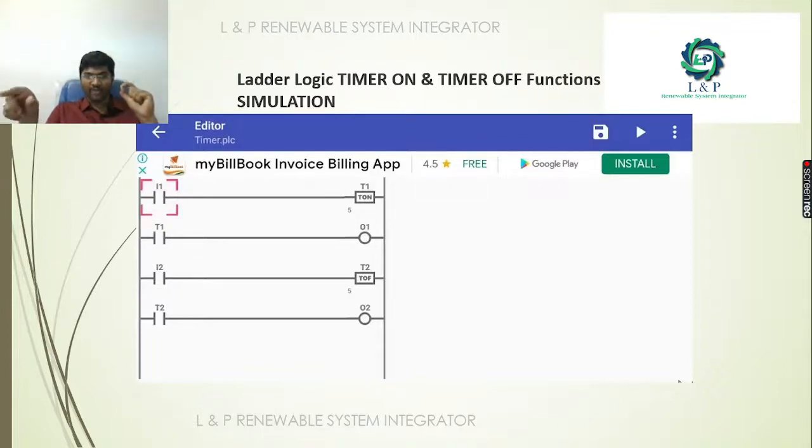If it is an off delay timer, when the switch is on, the output won't be on. When we disable the switch, it will count 5, 4, 3, 2, 1, and then the output will be off. So this is how an on delay timer and an off delay timer will work.